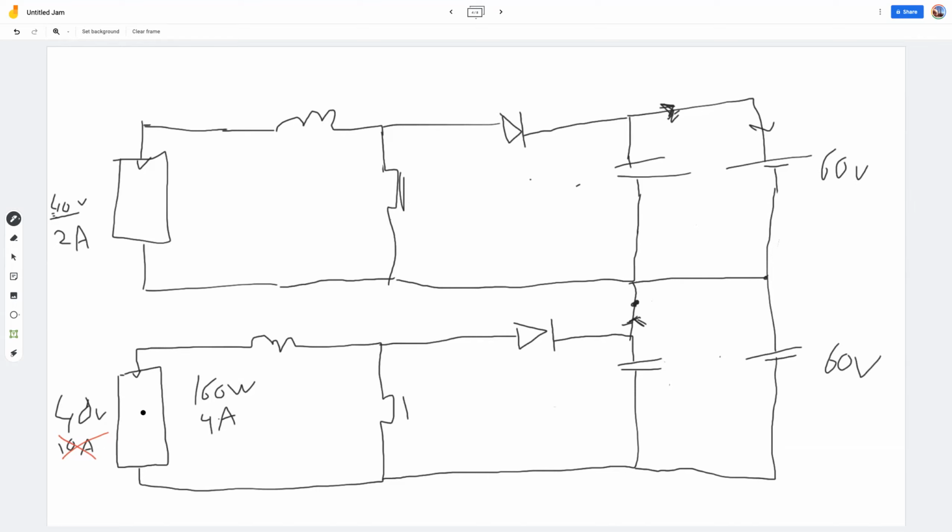And now the top and the bottom MPPT work independently from each other. They can both operate with a boost factor of 1.5 and they can both run at their maximum power point. Zach, are you still here? Can you see how this works? And can you also see any issues this would generate for your solar car system in general?